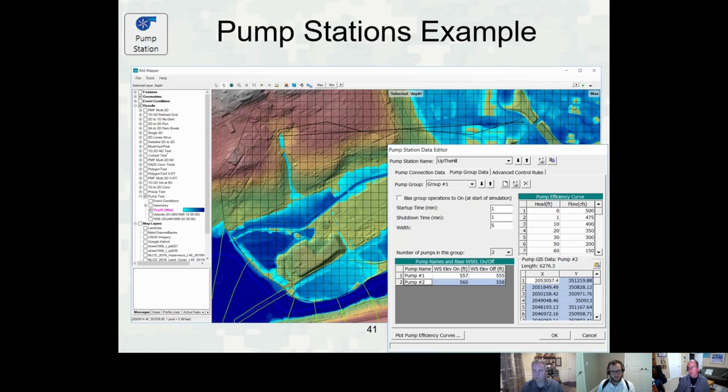You just have to use a really small time step. Sure. Yeah. But the other problem is that when you have water going over an embankment and you're using a Weir equation, if the water on both sides is almost the same elevation, well, in RAS, it has to use this curve to account for submergence. And the curve at high submergence is rapid bouncing of water and big changes in flow. It's large changes in flow for small changes in water surface. And that causes the bouncing because you get big fluctuations in flow for very small water surfaces. And that's really the problem. It's the Weir equation and how we handle submergence on a Weir equation.